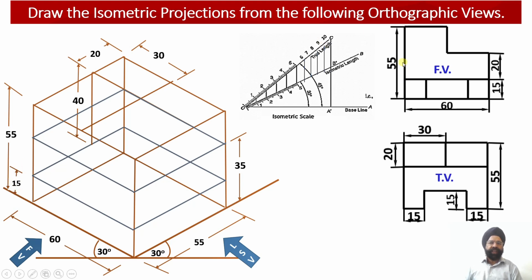Now having located this vertical edge of the vertical web over here, now I need to evaluate this vertical edge starting from this point and starting from this point over here. So from this point I am going to draw a vertical projection line. This vertical edge will be having the height which is equal to 20 millimeter. We can check the total height happens to be 55 millimeter.